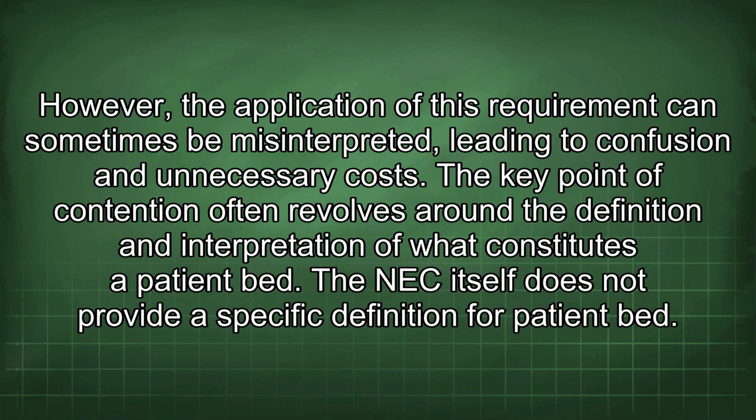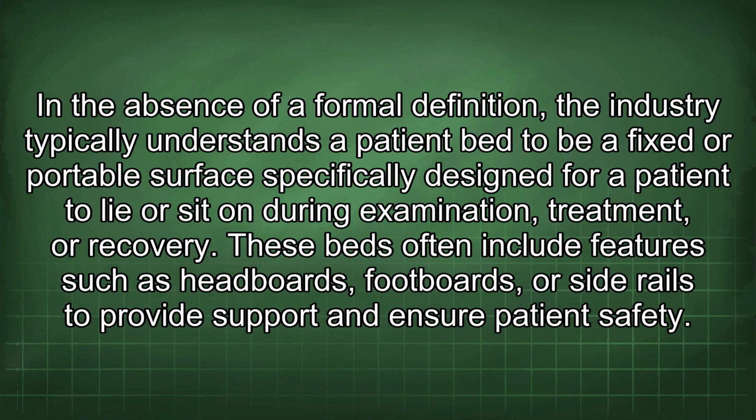The key point of contention often revolves around the definition and interpretation of what constitutes a patient bed. The NEC itself does not provide a specific definition for patient bed. In the absence of a formal definition, the industry typically understands a patient bed to be a fixed or portable surface specifically designed for a patient to lie or sit on during examination, treatment, or recovery. These beds often include features such as headboards, footboards, or side rails to provide support and ensure patient safety.